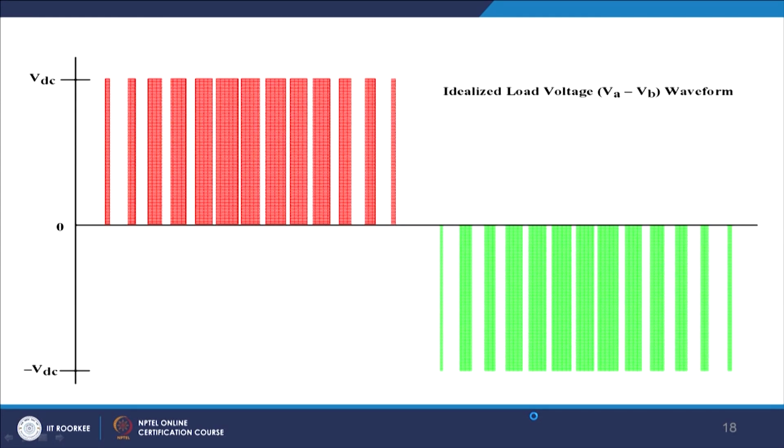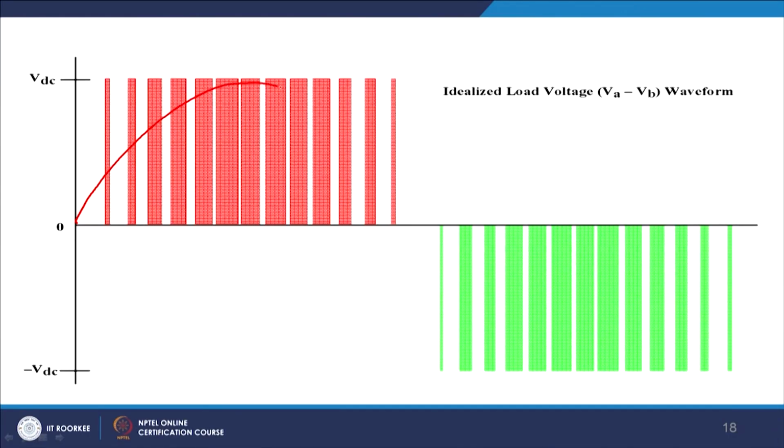And what is the advantage of it? The advantage is that its instantaneous voltage error is half. Let us consider that this is the sine wave where both areas have matched, and for this reason you can find that the voltage error here will be only half of the error voltage compared to the bipolar.